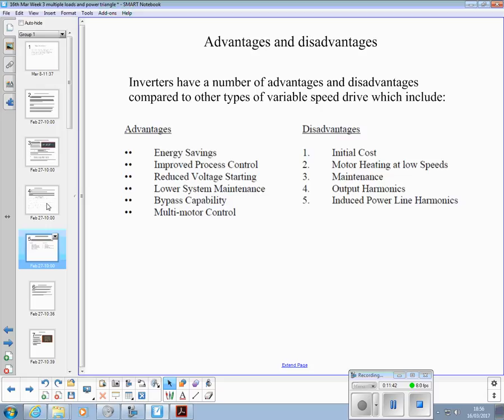But if you've got a 50 hertz supply and you go to 60, you are going to start losing some voltage because you can't get more out than you're putting in. So you're going to drop a little bit of torque. I'm not an expert in the field, but I would think in most circumstances you're going to be okay to go at 60 hertz, even if your input supply is 50. But beyond that, you're moving into risky territory, particularly if your load is big, because your torque is going to start to drop. How are you going to then move your load properly?